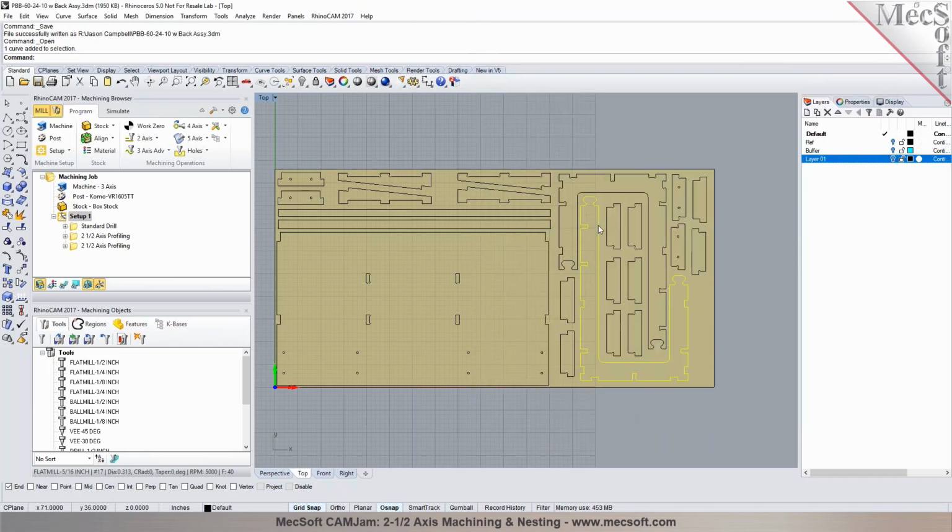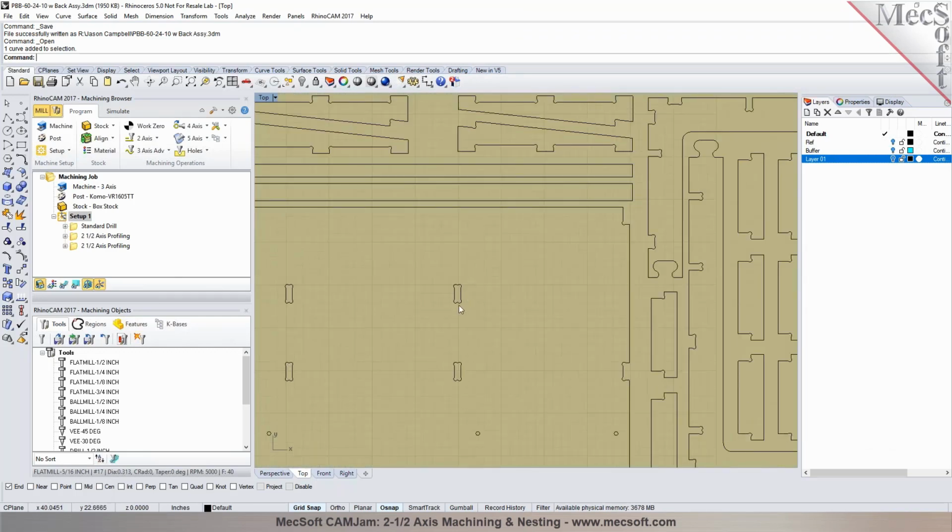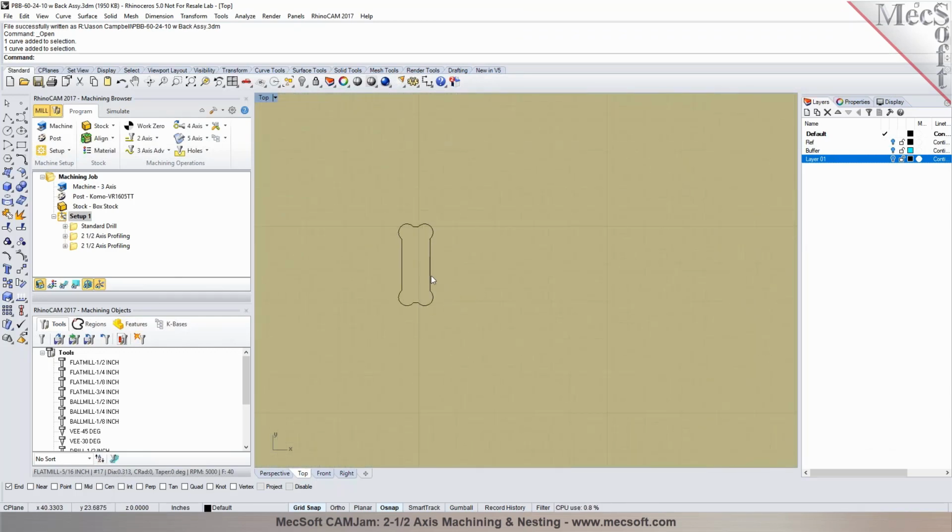So if you make a change to the drawing, you want to update it. For example, in here, let me go back and take a look at this part right here. I'm going to modify this. I'm going to scale this part. I'll pick the snap tools in here in Rhino. I'm going to find the midpoint of this, using the smart tracker to get the midpoint of these two. So basically, I got the intersection of the two. And then for the scale reference point, I want to make it 1.5 times.